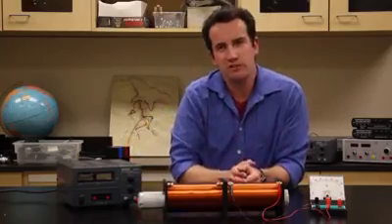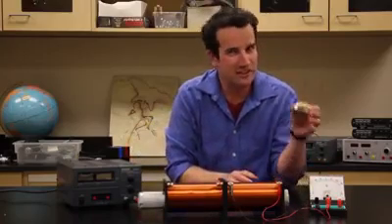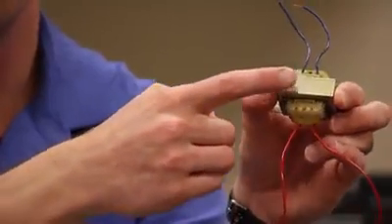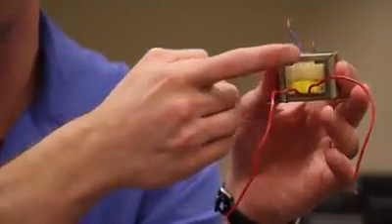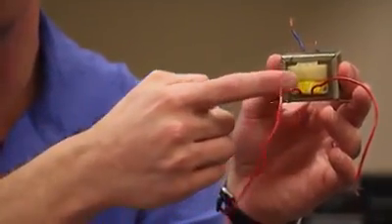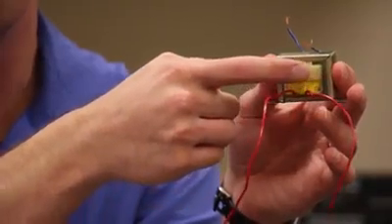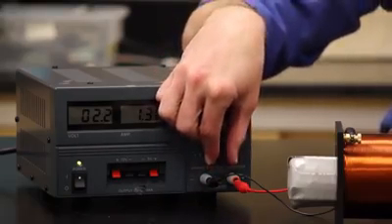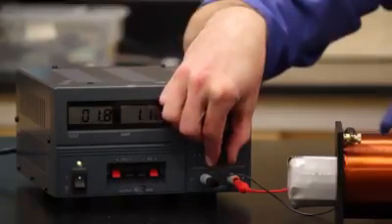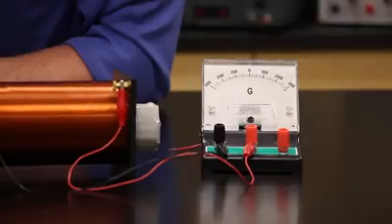The transformers found in home appliances usually look like this. Here are the coils, which are wound on top of one another, and this surrounding structure is soft iron shaped to guide the magnetic field lines back around and through the coils. Typically, a transformer is supplied with an alternating current, since if the magnetic field does not change, the transformer would not work. Incorrectly using DC for the input of a transformer, like say a battery, might even damage it.